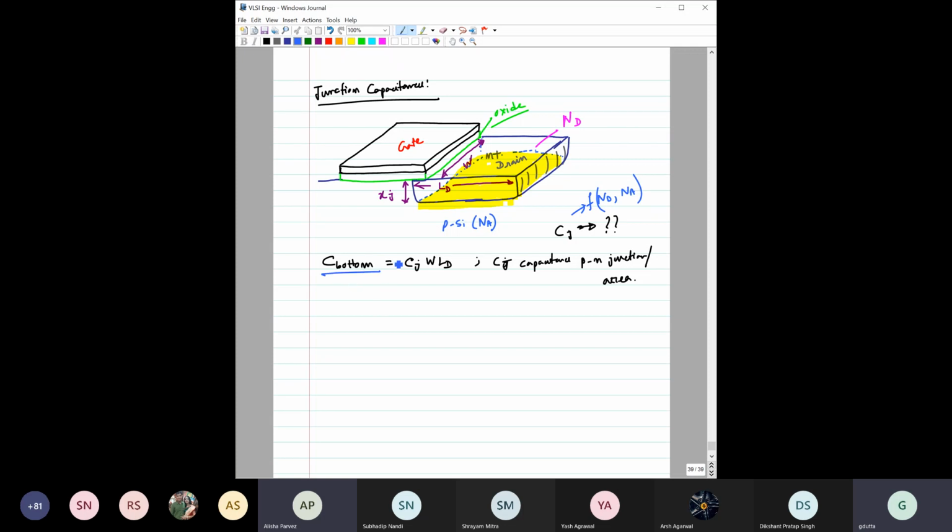So you know then what this C bottom part is, but along with that we can also see other components would also be present. For example, the capacitance will also be there because of this surface, this surface, this surface, right? Three side surfaces. Now the question is whether these capacitances, like per unit area capacitance, will also be Cj. The answer is no, because